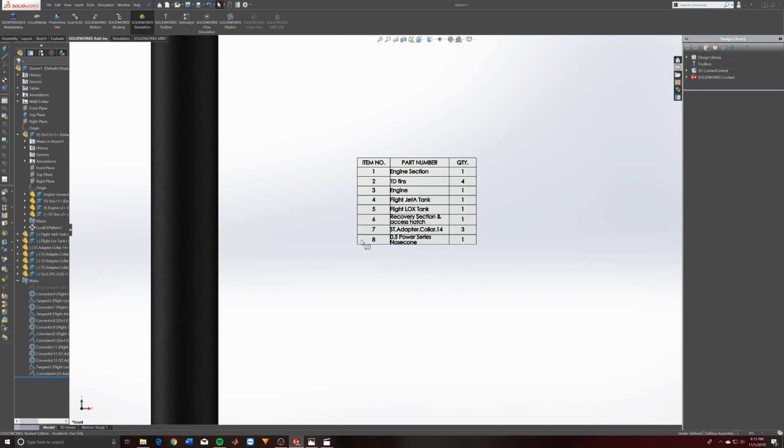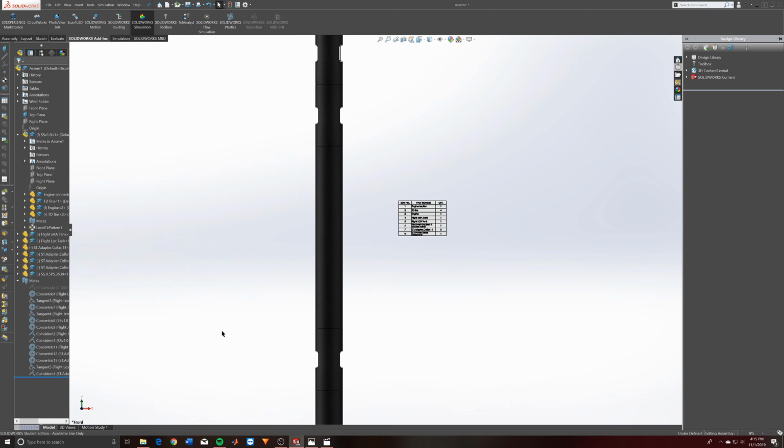And it'll tell you the description of the bolts, the nut, what kind of threading count, all that information, and it'll keep track of how many you need as well. So that's a really useful way. Instead of having to go around and count the bolt holes, you can import bolts into it and run analysis on those.